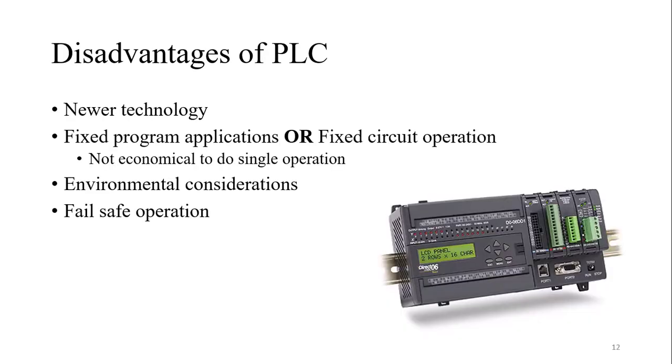Fine. There are disadvantages. In India, there are some disadvantages because this is newer technology. Very simple. It's newer technology. Nobody wants to change it. Clear? Secondly, fixed program application of fixed circuit operations. It means it is not economical for a single operation. Those industries in which various operations are to be maintained, then this kind of PLC programming could be used. If you are doing one operation all the time, there is no need to have it because it is not economical.